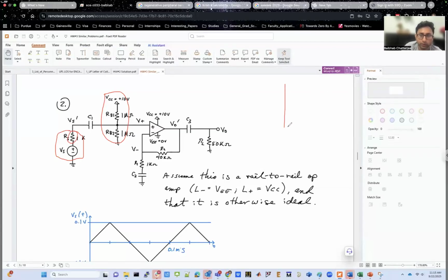You already learned from your voltage transfer characteristics that if you plot your input voltage on the x-axis and your output voltage on the y-axis, your voltage transfer characteristic looks something like this. And to have the maximum amount of gain, you want to be in the middle of this voltage transfer characteristic. You do not want to be at 0 DC voltage, because 0 DC voltage is here, right? The point 0 in your 0, 0. So input voltage is 0, output voltage is 0, or output voltage is maximum in this case. So 0, let's say V max. That point is over here.